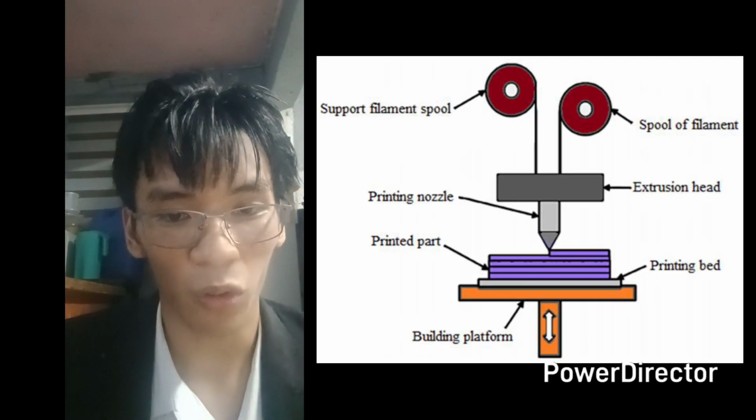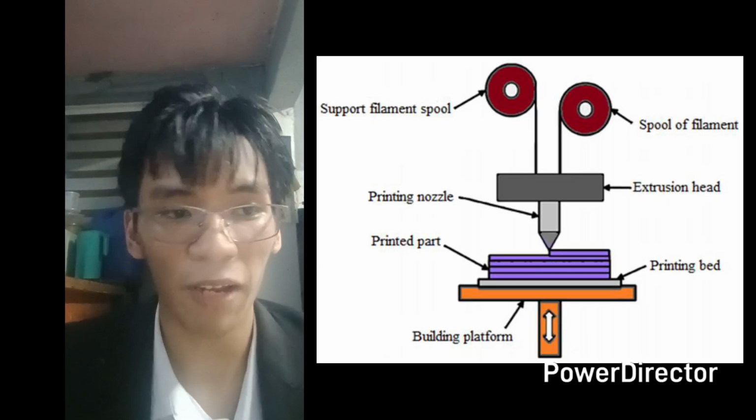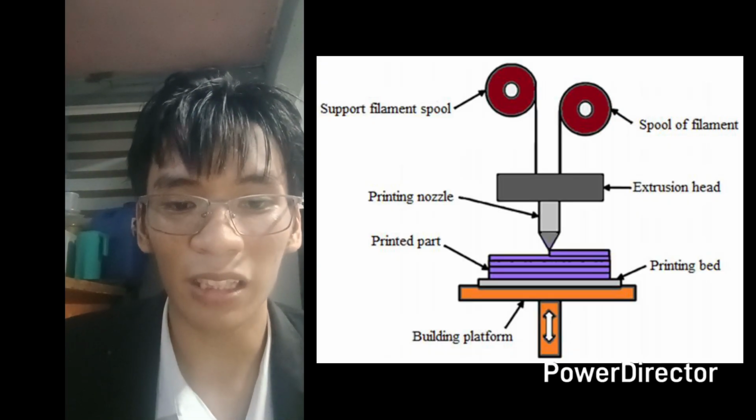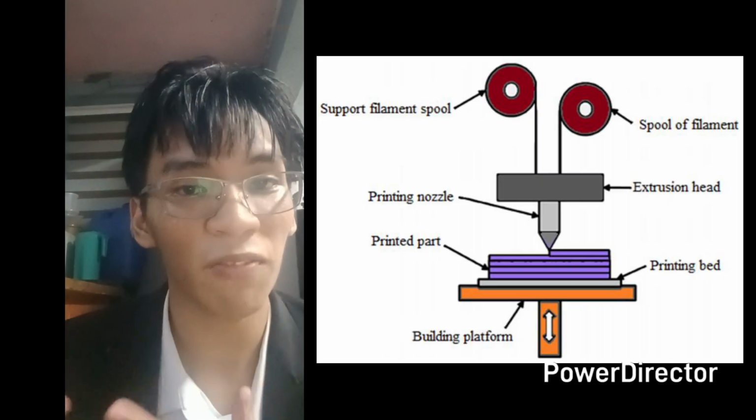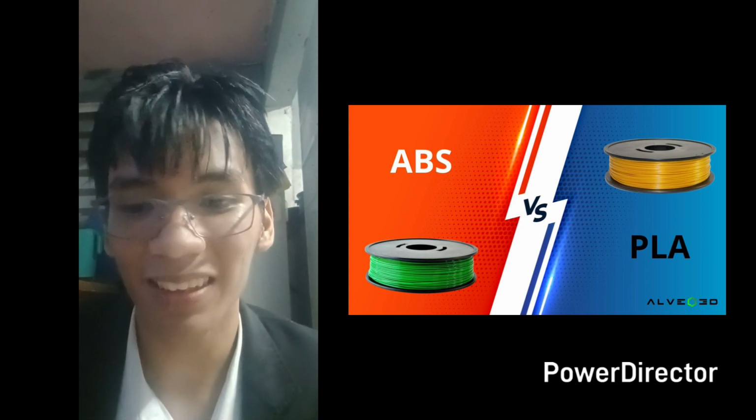Sometimes, other filaments or chemicals are used to help with improved layer adhesion, flame retardancy, flexibility, and other characteristics that might be beneficial for the object. The most commonly used materials for this type of 3D printing are polylactic acid and acrylonitrile butadiene styrene, each having their own different characteristics, pros and cons, depending on the type of object you want to be created.